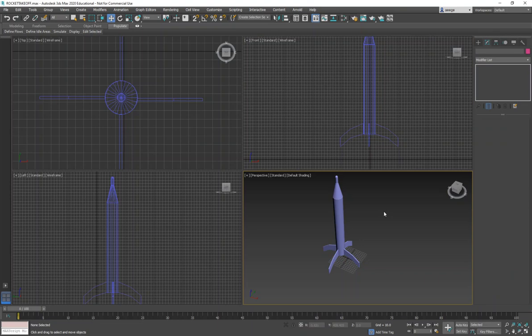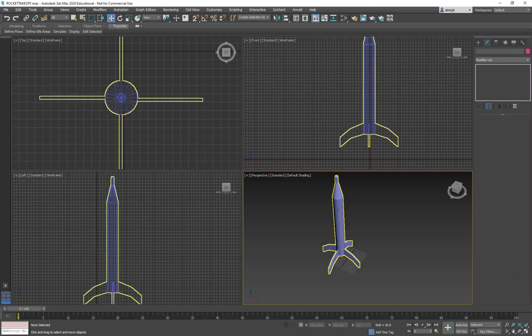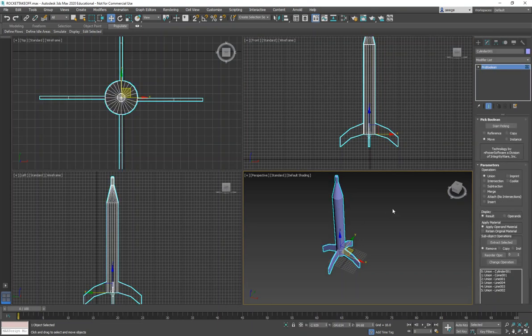I suggest you click anywhere outside on the screen and then click on the object again, to see that the object is surrounded by a blue line, which indicates that it is selected. Now move your cursor to the ribbon at the very top. If you count from File, Edit, Tools, 3, 4, 5, 6, 7, 8, the eighth group of commands is Animation. So click on Animation.